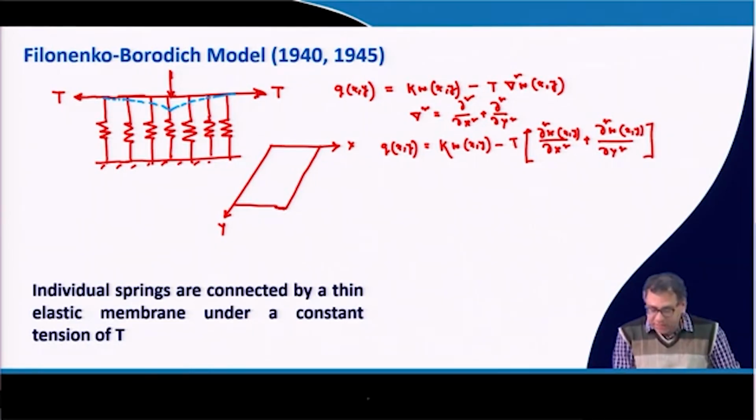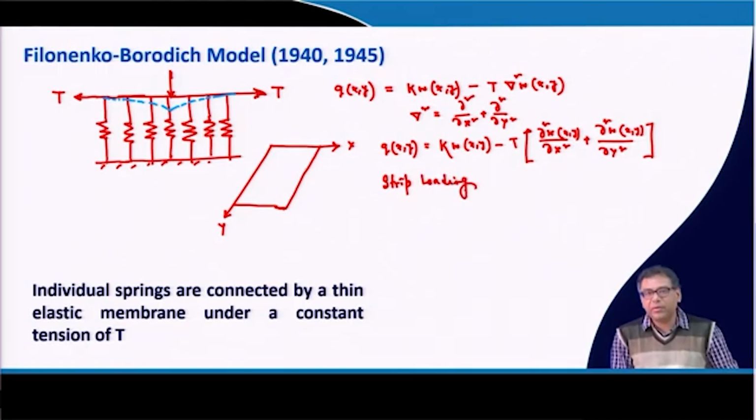Okay. And now, for the strip loading or the continuous loading, strip loading means where the length of the loaded region is much longer than the width of the loaded region. In such a case, you will get the influence only in the x direction, the other direction will not get any influence, and that is called the plane strain condition.